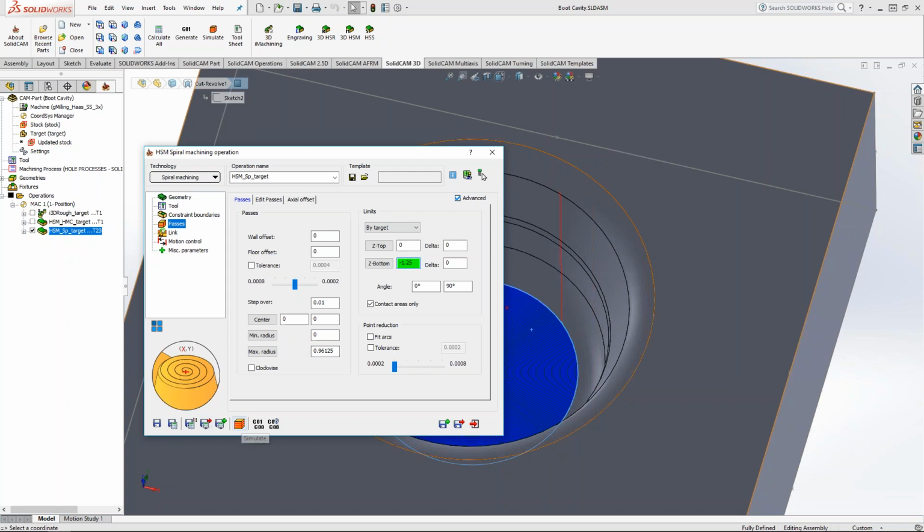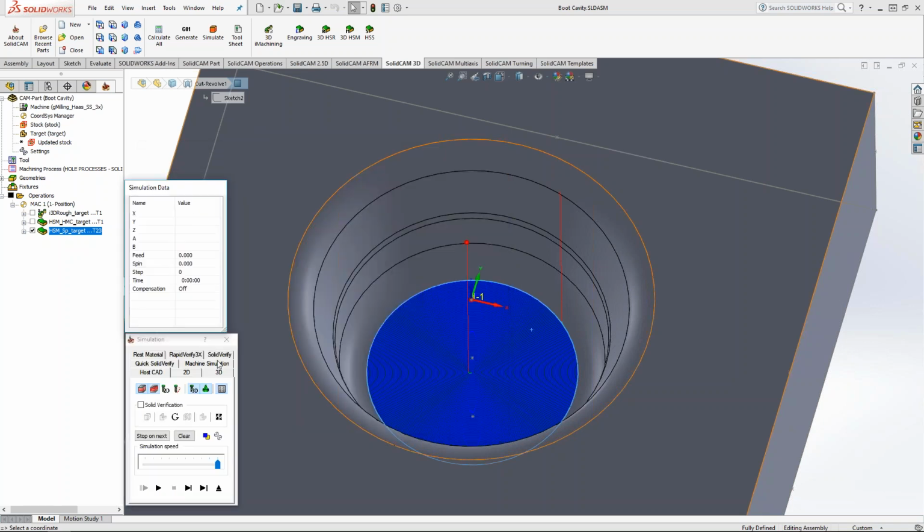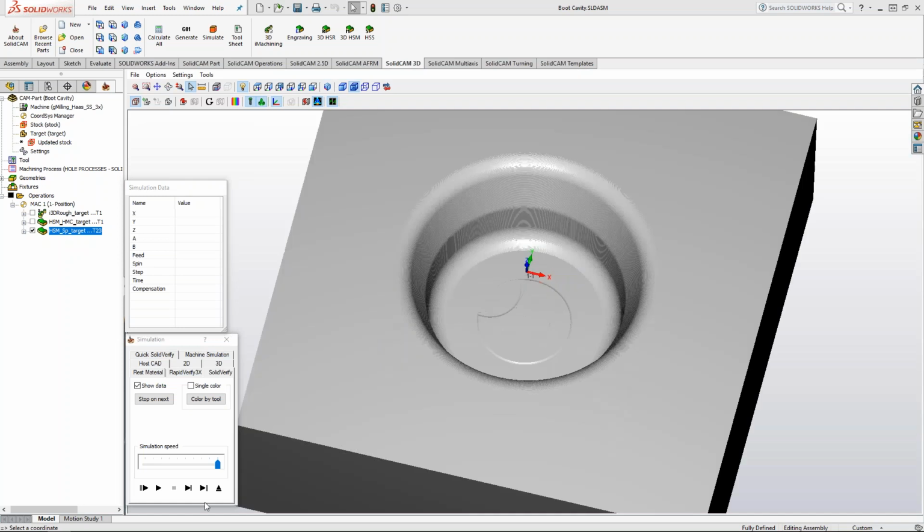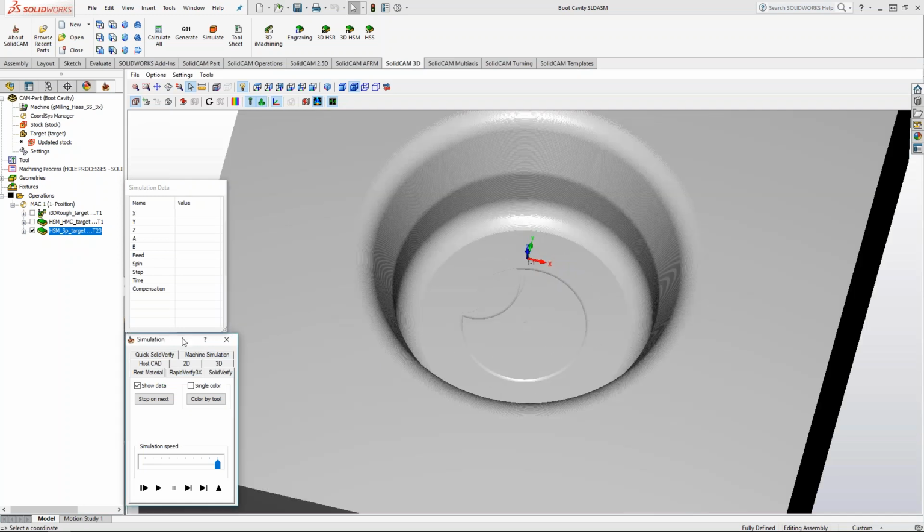Gotcha. Now on this particular part, a question came through. Were you running the 3D machining dry, or did you run coolant with that? I would assume you did air. No, I did air blast on that. Again, the tools that I used, the AlTiN carbide, running at the high feed rates that I did, it was recommended from the vendor to run dry.